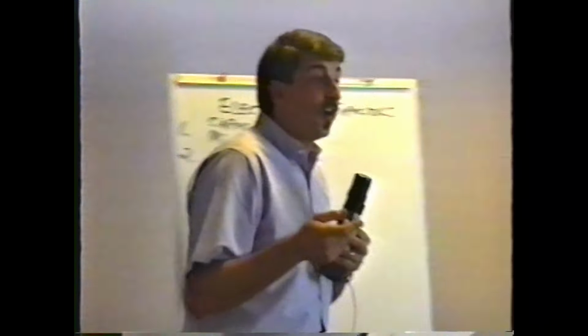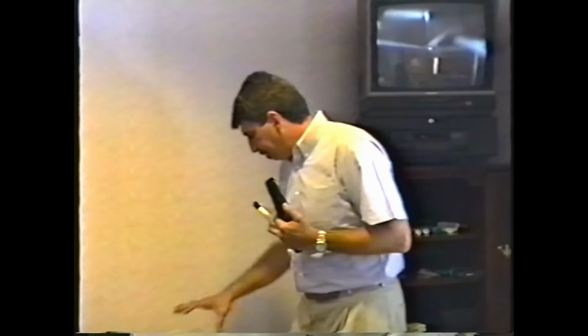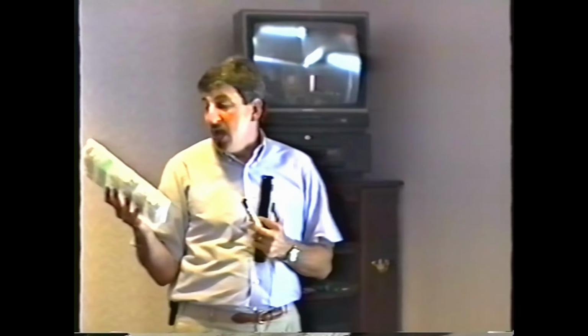You have to substitute parts a lot. When you have to substitute capacitors, you can always use a capacitor with a higher voltage rating. I do this a lot. For instance, I carry around these boxes here, and they're basically just like tackle boxes full of different kinds of capacitors. One common value that I use a lot is 10 microfarads. And in here I've got 10 microfarad, 200 volt capacitors.